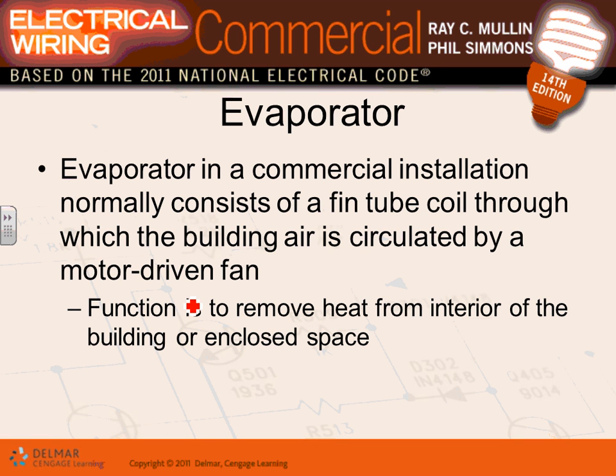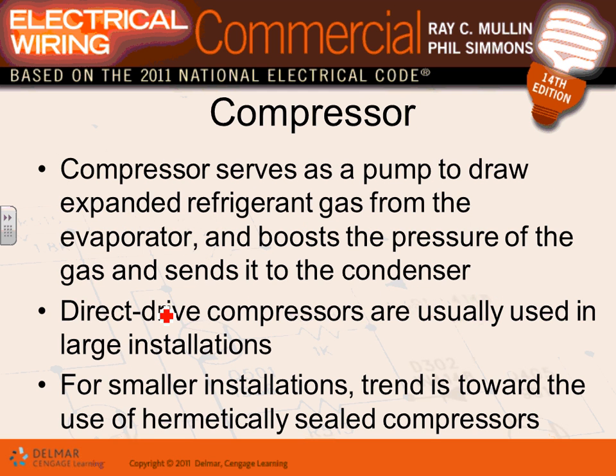We talked about the function of the evaporator. The function of the evaporator is to remove the heat from the interior of the building or the enclosed space. You have a big blower blowing the air right through the liquid. The liquid will pick up the heat and circulate that heat. So that's the evaporator.